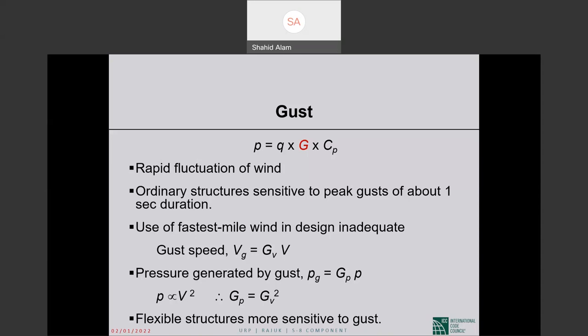So for those buildings, we are allowed to use a gust effect factor of 0.885. So we bring the 3-second gust speed actually down. And then for the more flexible buildings, we calculate the gust effect factor, which typically comes out above 1, but doesn't have to. So it has changed.